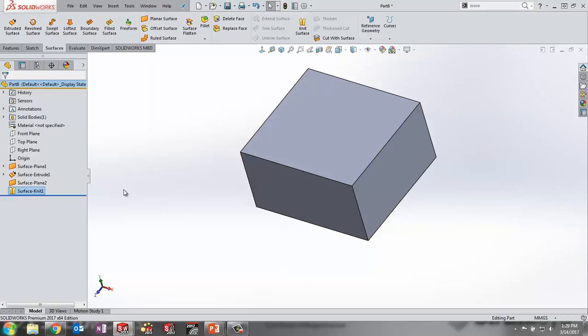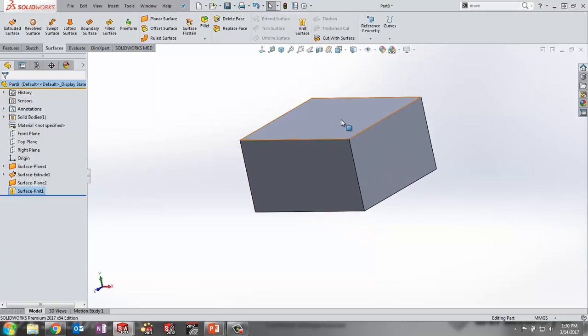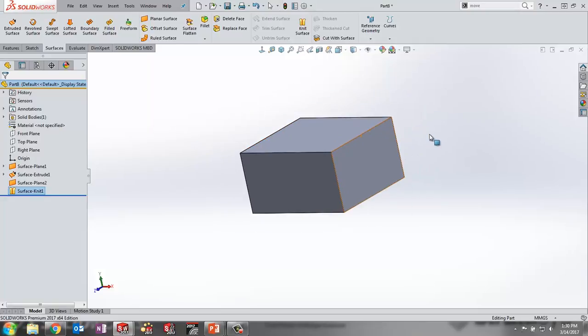So like I said, your surface modeling isn't going to be the preferred method. It's still going to be solid modeling. But in the background, SolidWorks does surface modeling for you. So that's the approach of, okay, when I need to do something that's pushing the boundaries of solid modeling, that's where we get into surfacing, because you have the ability to do more steps. So I just wanted to show this approach to say, hey, look, you can do everything in surfacing that you can in solid, but in solid you don't have the freedom that you do inside of surfacing.